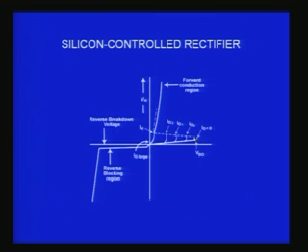Once it conducts, it means it is switched on. So the voltage across the SCR will be a very small voltage somewhere here. This should be something like 100 volts, 200 volts, but this voltage will be almost close to 1 volt. So it will come quickly to this conduction region, and if I now keep increasing the applied voltage, you would find the current will increase like a normal diode, right, with very little change in the voltage across the device, but the current will increase enormously depending upon the voltage I apply.